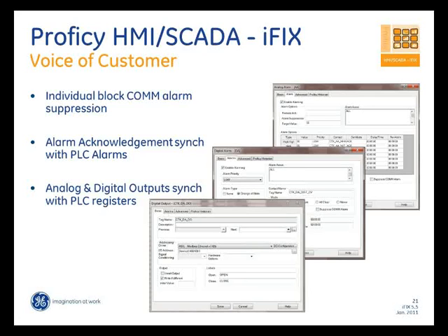The other VOCs that we put in is support for Office 2010 and the capability to have a native ODBC driver into SQL 2010. What we found out was the native SQL driver, the structure of the timestamp in SQL 2010 is slightly different than the previous versions of SQL, and if you use the native SQL driver, it kind of broke your alarm ODBC, or it broke any of your VisiConnects or any alarm timestamp queries that you did on SQL 2010.